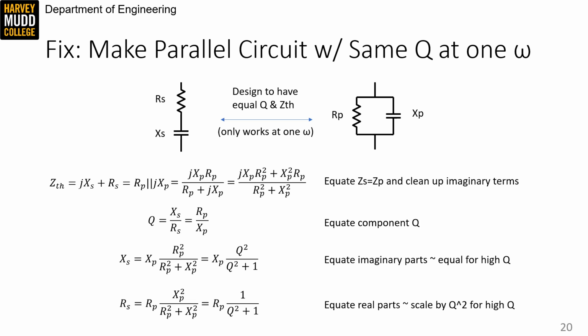This is a useful impedance transformation that we can achieve just by putting a load resistance in series with an inductor or a capacitor, and we'll start using it very soon.